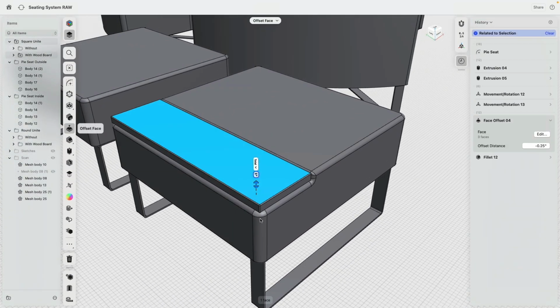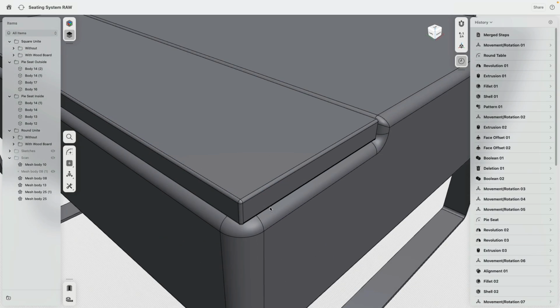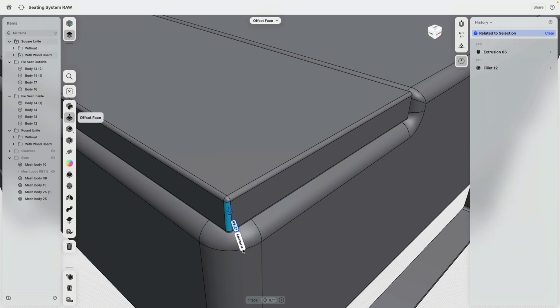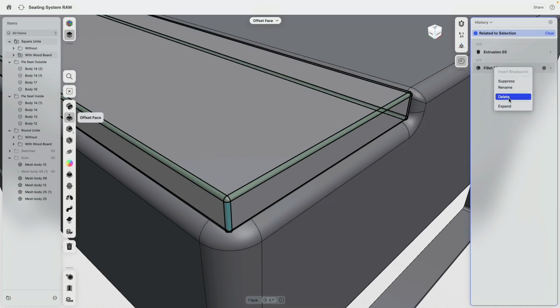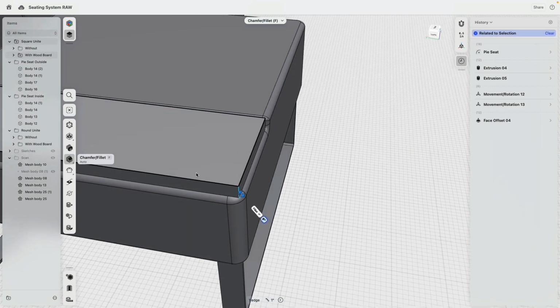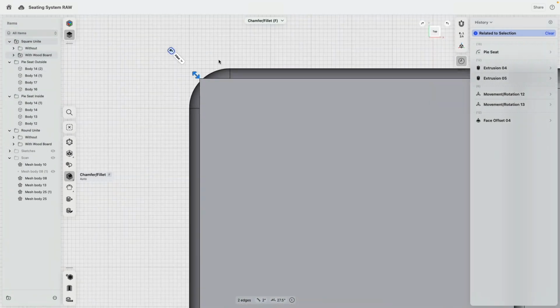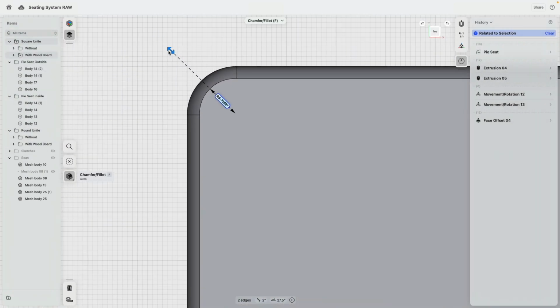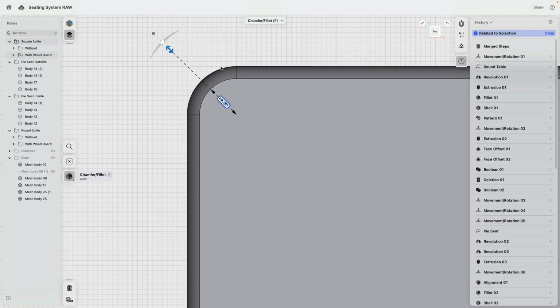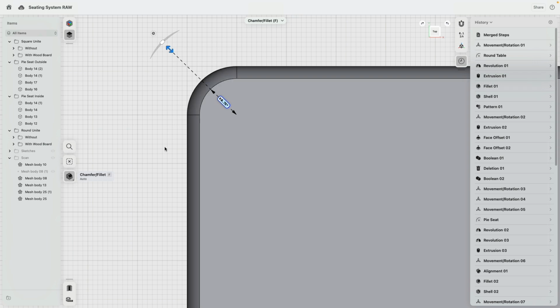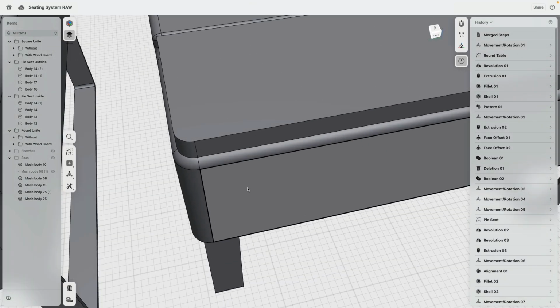Now this is the way design sometimes also evolves. I have here a big fillet and a tiny fillet. So maybe this is fillet 12. Let's right click, delete fillet 12. And what I will try to do instead is go to a top view and round this a little bit, so it looks like it has a very similar radius. Yeah, this looks like this. Okay, beautiful.